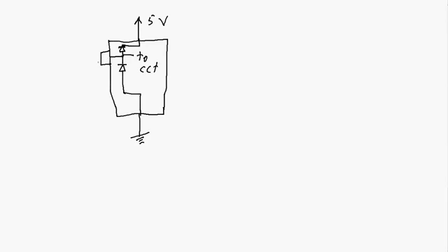Now, if this voltage falls below 0 volts by some amount, depending on the forward voltage of this diode, this diode all of a sudden becomes forward biased, and we will have current through this diode as opposed to over voltage into the circuit. So we're going to have clipping at something around minus 0.7 volts or minus 0.3 volts, depending on the type of diode this is.